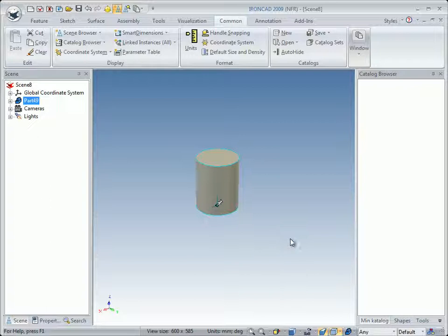When you have made a part in the 3D scene, you can left drag this part out to the catalog. You can drop it there. As you can see, there's a plus sign at the cursor. That means that you get a copy of that part, and this part is named Part 49, and it's the same name as you can see in the scene browser.